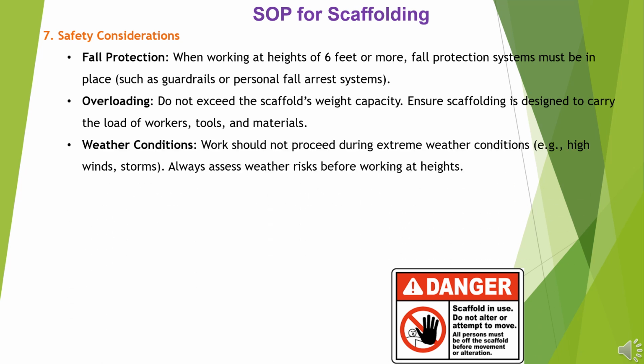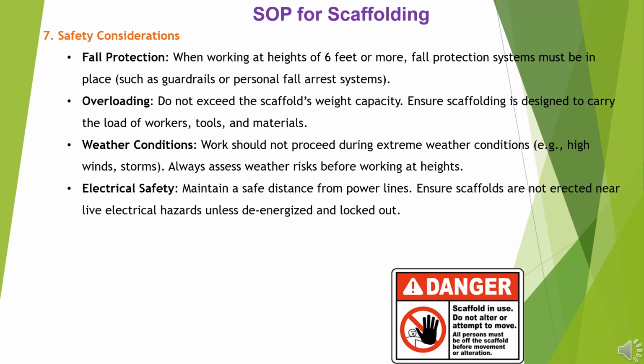Weather conditions: Work should not proceed during extreme weather conditions, e.g. high winds, storms. Always assess weather risks before working at heights. Electrical safety: Maintain a safe distance from power lines. Ensure scaffolds are not erected near live electrical hazards unless de-energized and locked out.